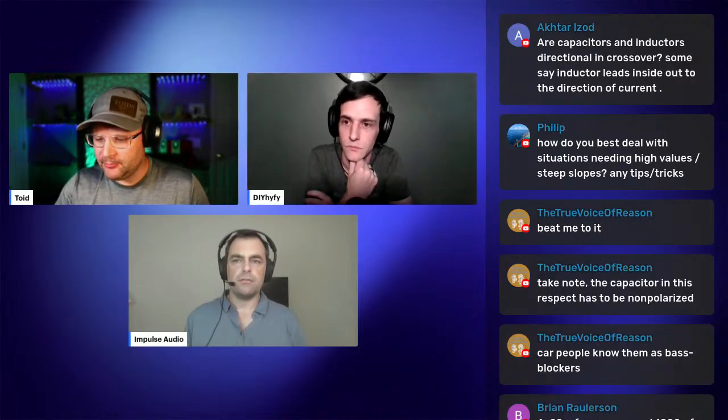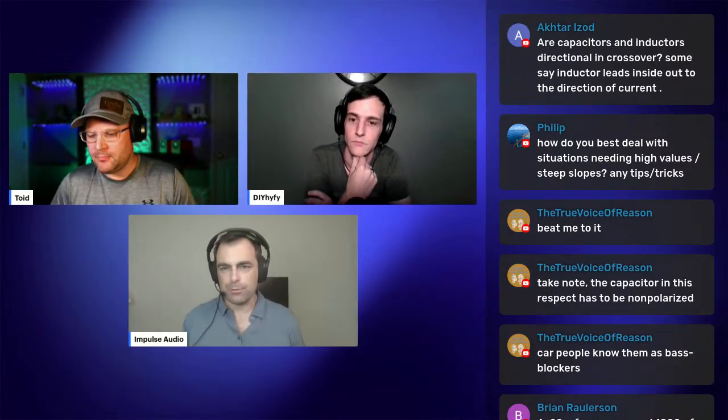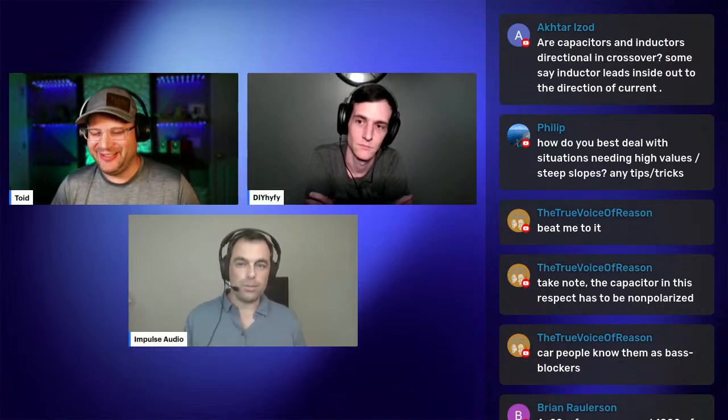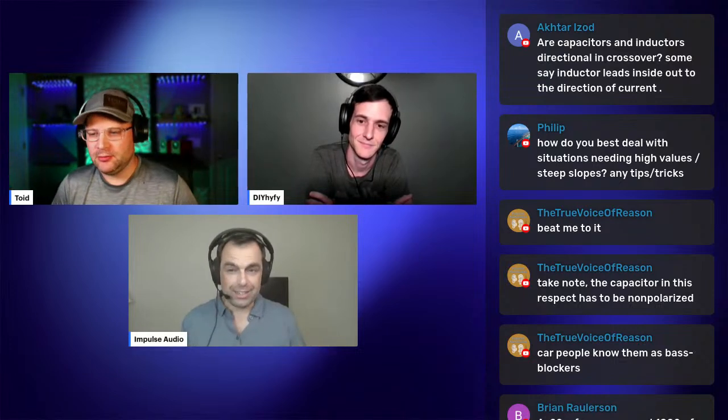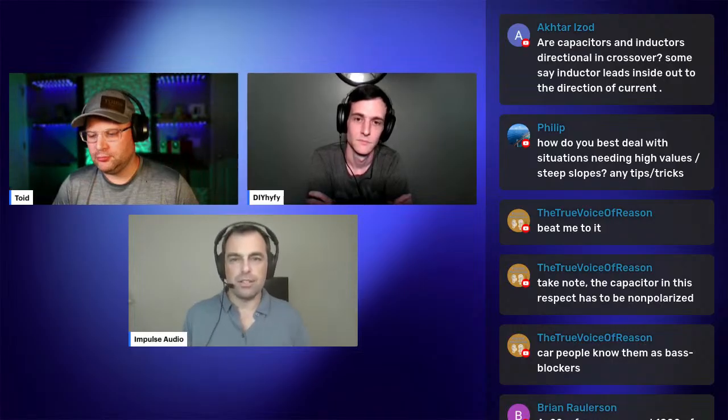If you're doing that to protect your amp or something, because your amp is rated for 8 ohms, it's going to be happier playing 4 ohms at a suitable level than you cranking it up, blowing all this wattage through a cooking hot resistor. Yeah, it's very counterproductive to put a resistor like that.